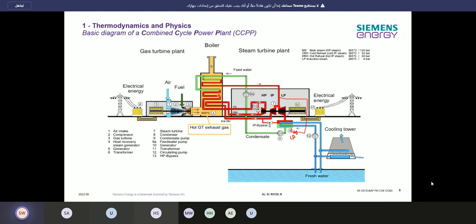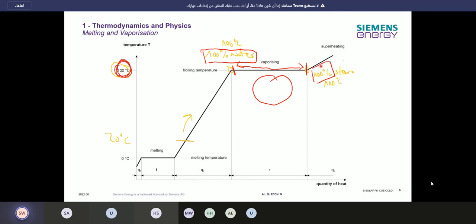And when we go further to the superheater, where we're superheating our steam, from here to here, of course, we want to make sure that we're not getting any water particles in there. So from the evaporator outlet, it will be 1-2 Kelvin above the boiling temperature, so slightly superheated by 1 or 2 Kelvin, to make sure that there are really no water droplets getting into the superheater.